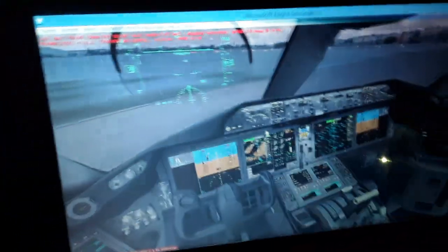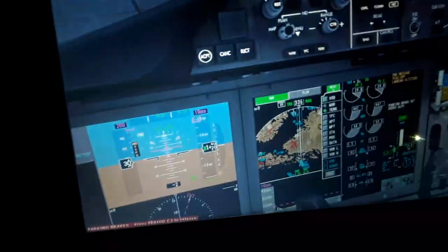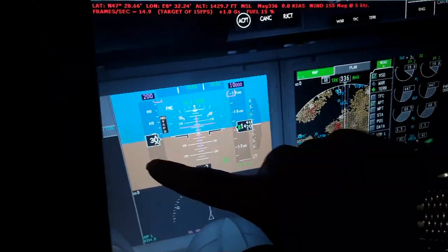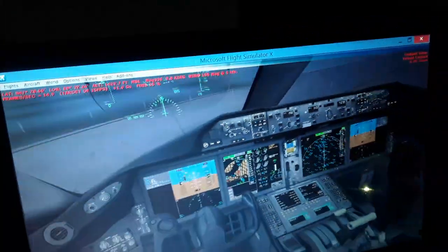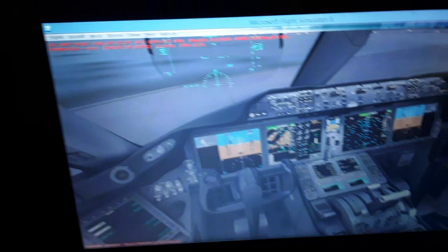When you're flying, you will see the stall speed displayed below your airspeed, with the yellow and red indication down here. You need to have an airspeed and angle of attack that avoids the stall. This will also calculate the horizontal trim stabilizer for takeoff, 4.35 degrees. Also the flaps we're going to use for takeoff, 15 degrees.